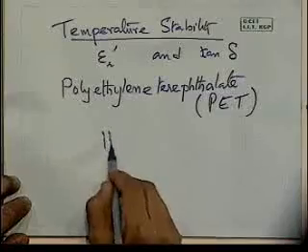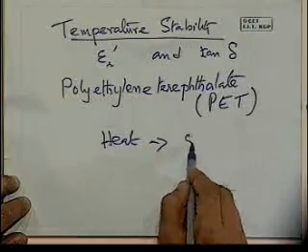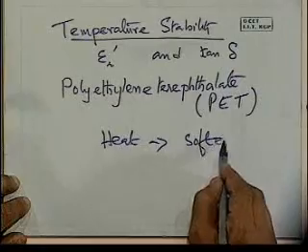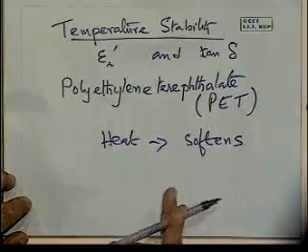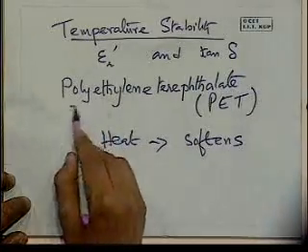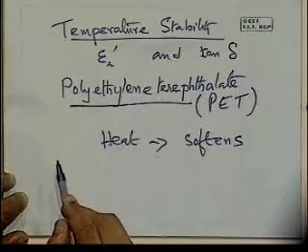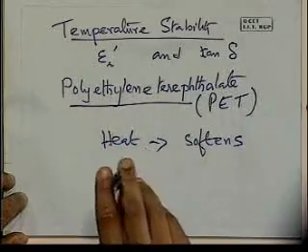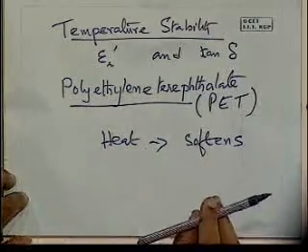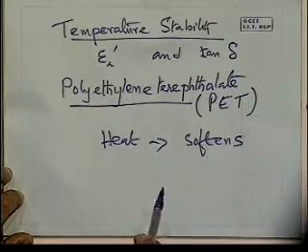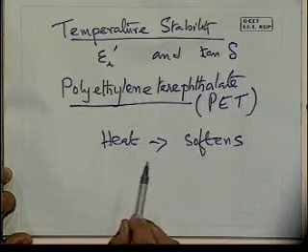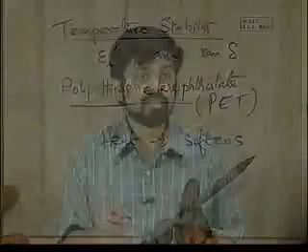But as we heat it up, the polymer becomes soft. And when the polymer becomes soft, the dipoles that exist, it's a polar material, are now within that softened material able to respond much better to the applied frequency. So with increasing temperature, we see that it is able to function to higher frequencies, because now in the softer matrix, it is able to flip around more easily.